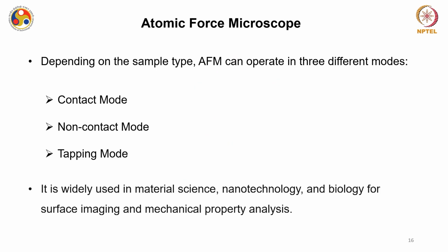So depending on the sample type, AFM can operate in different modes. Mostly 3 different modes are popular: contact mode, non-contact mode, and tapping mode. As the name suggests, contact mode means the tip is in direct contact with the surface of the sample.